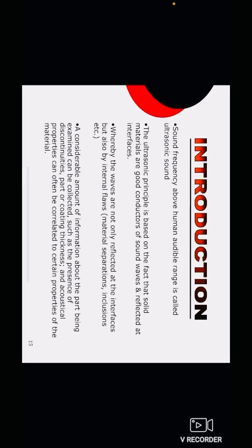The ultrasonic principle is based on the fact that solid materials are good conductors of sound waves and reflect at interfaces, whereby the waves are not only reflected at the interfaces but also by internal flaws, material separation or inclusions, etc. A considerable amount of information about the part being examined can be collected, such as the presence of discontinuity, part or coating thickness, and acoustical properties can often be correlated to certain properties of the material.